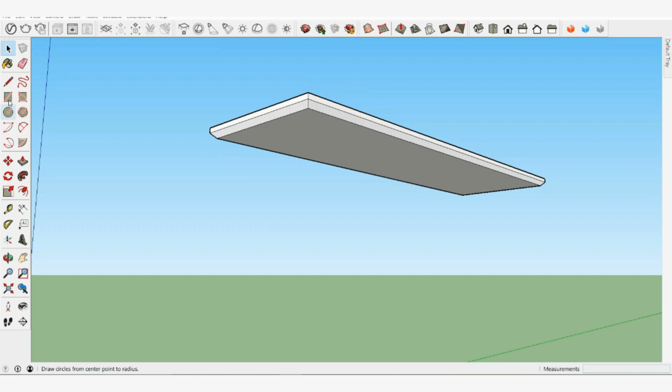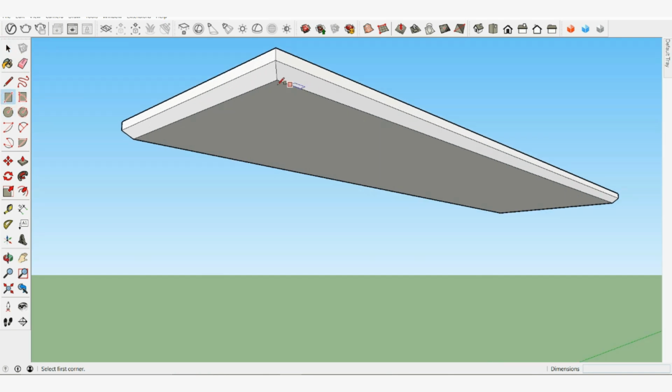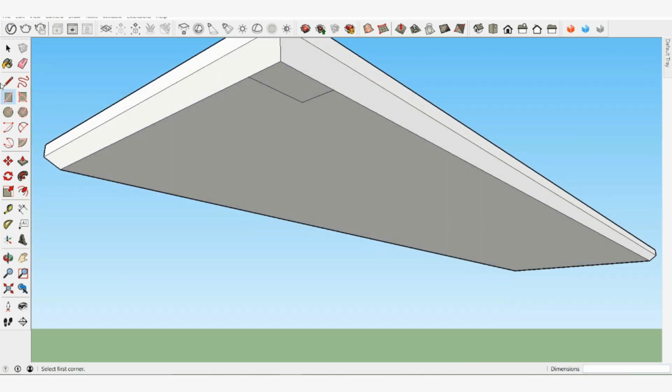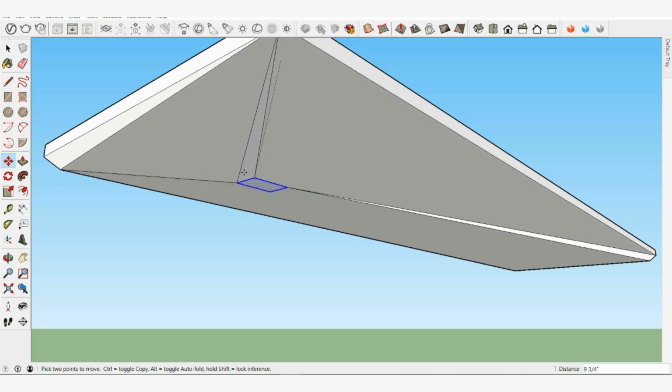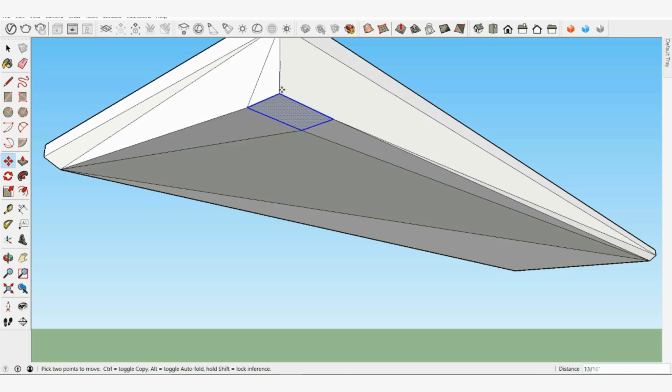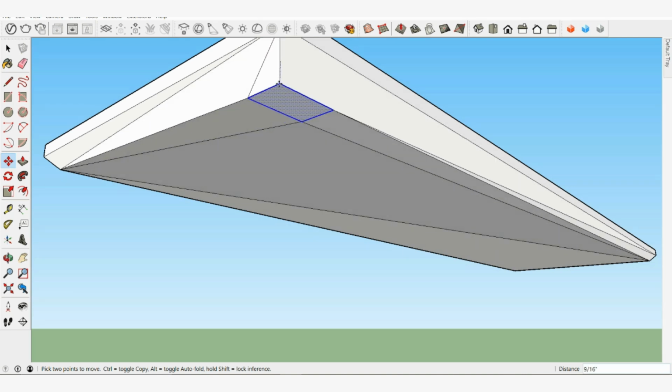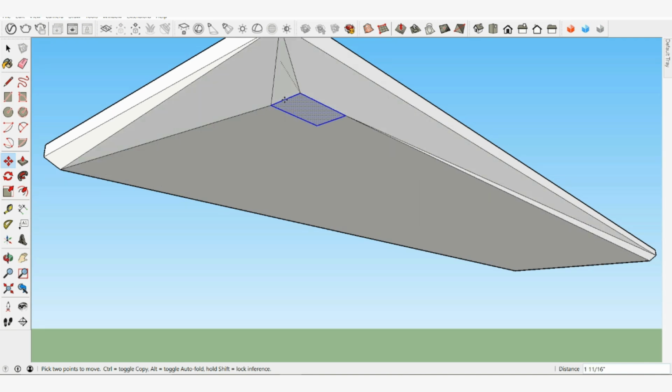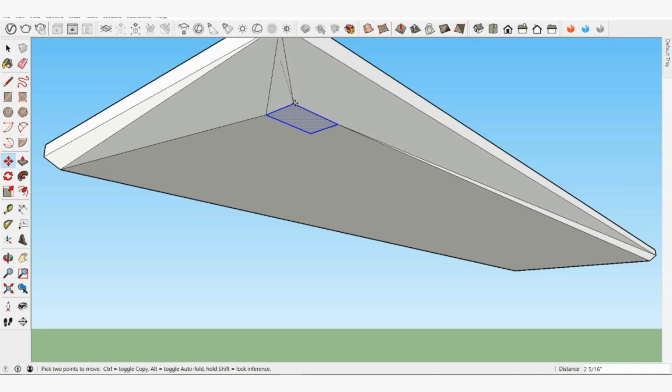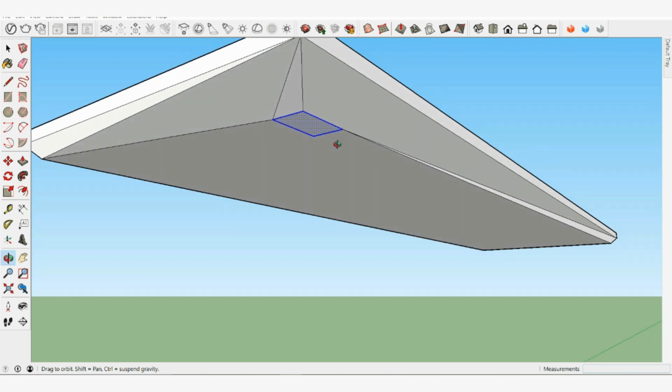However, before using push-pull, let's say we change our mind and want the leg to be inset from the edge instead. If we select and move this surface, however, it begins to wrap the tabletop. By drawing it on top of the other edges, those edges merged. This is a key behavior to making SketchUp fast and easy, but it's not what we want in this example. This is one of the primary uses of groups, which will isolate our geometry, preventing the edges from merging.